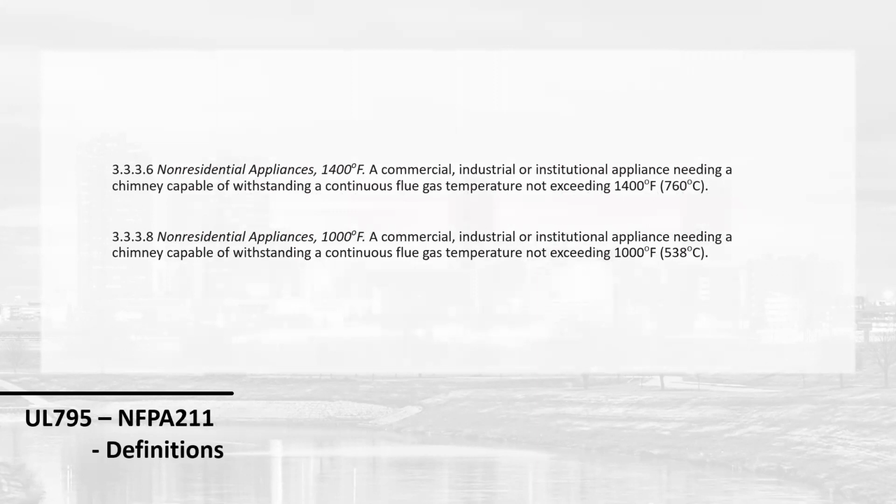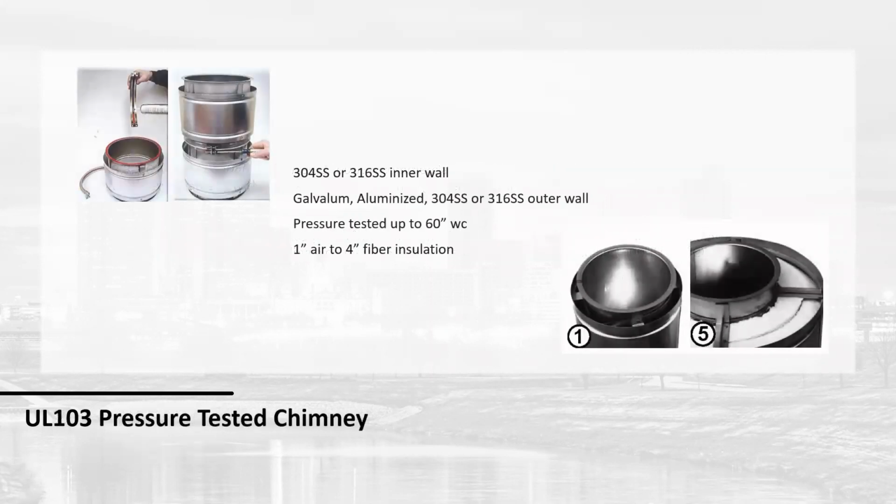You cannot exceed 12.5 million BTU input, and you cannot exceed 15 PSI of steam. So most of your fire tube, vertical tubeless, water tube type products, vent tube type products are going to be a 7095 building heating appliance. And the reason why that matters is because their flue temperatures can accelerate dramatically higher than what the 1738 pipe can handle. So they make a special UL 103 pressure pipe.